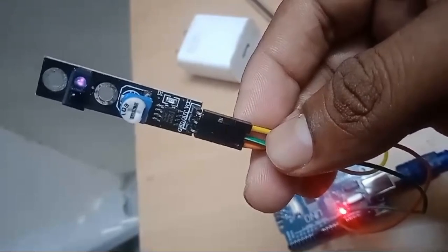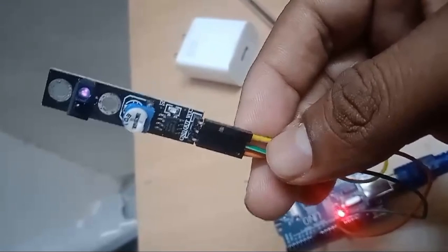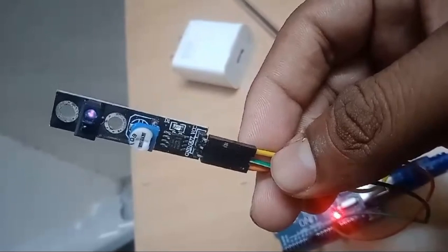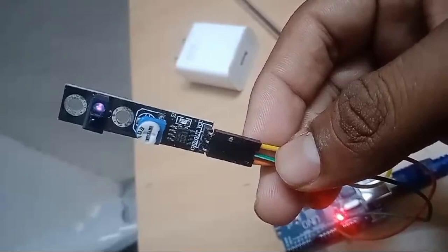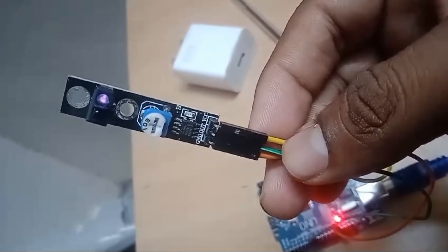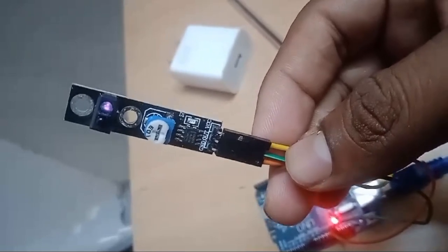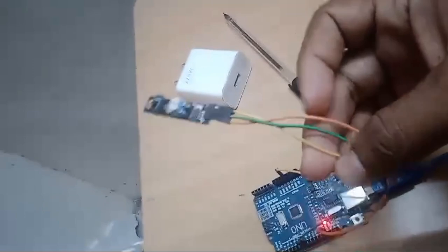There is only one output pin, and it is used as your sensor pin. The output pin's LED is by default on the sensor itself, so you do not connect that. And then VCC is the 5-volt power you are going to connect.